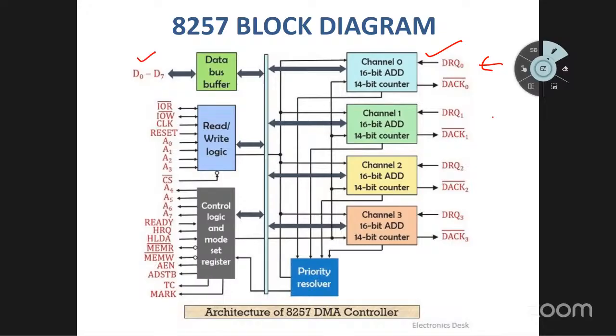The DMA controller gives the external device the DMA acknowledgement signal: the bus is ready, now you can access the memory. The connected device is now accessing the memory.